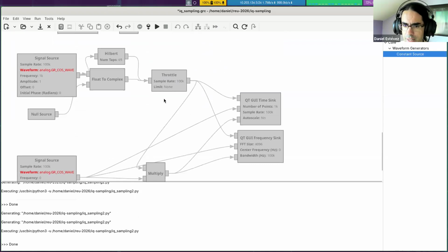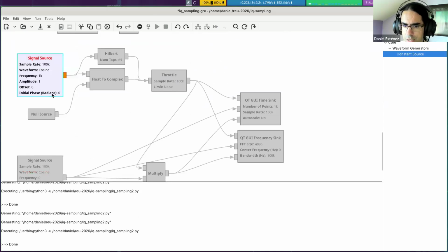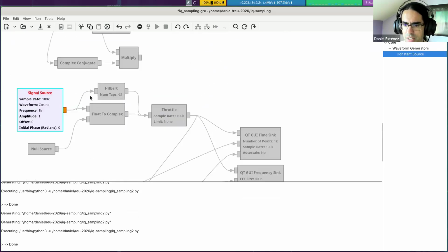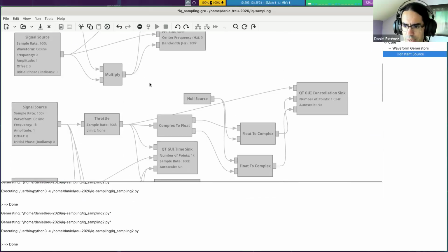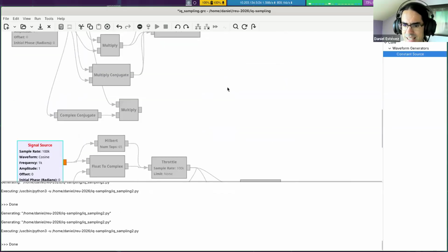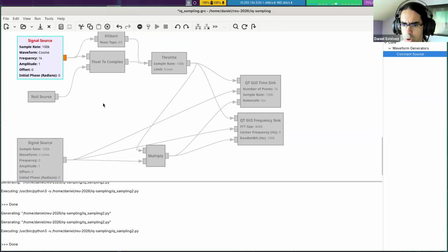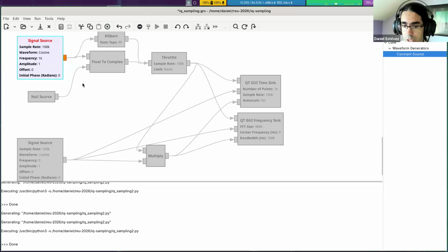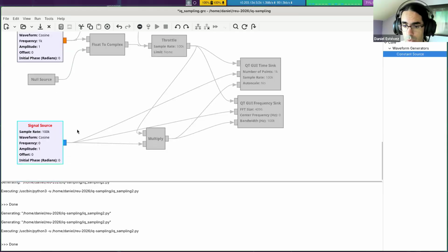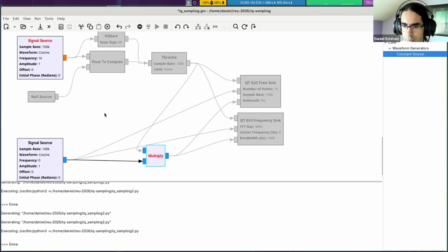And then finally, the last example I have here is how do we combine these things? We have seen one example here with real signals. The next example was with complex signals. How do we work if we have a real signal to begin with, which, for example, is what happens with the RTL-SDR stick. The signal in your antenna is real, it's a real voltage, but then you might want to work with complex signals and have a complex local oscillator. So how can we do that?